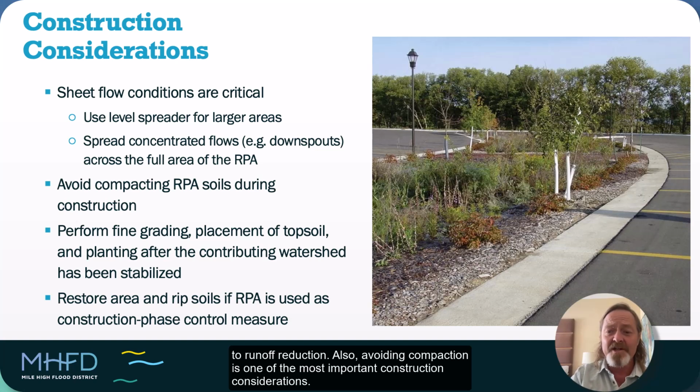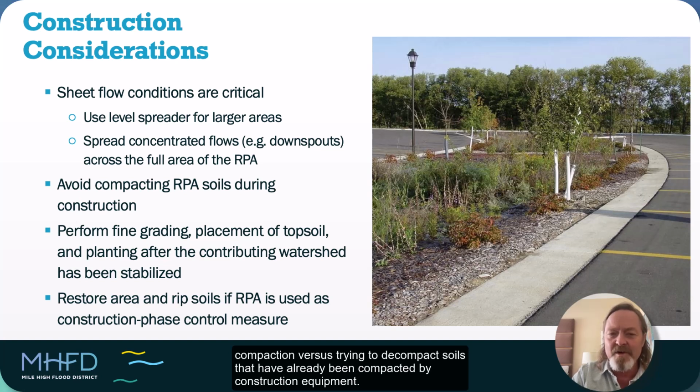Also, avoiding compaction is one of the most important construction considerations. Compaction can ruin an RPA before it even goes into service. And it's really preferable to avoid compaction versus trying to decompact soils that have already been compacted by construction equipment.